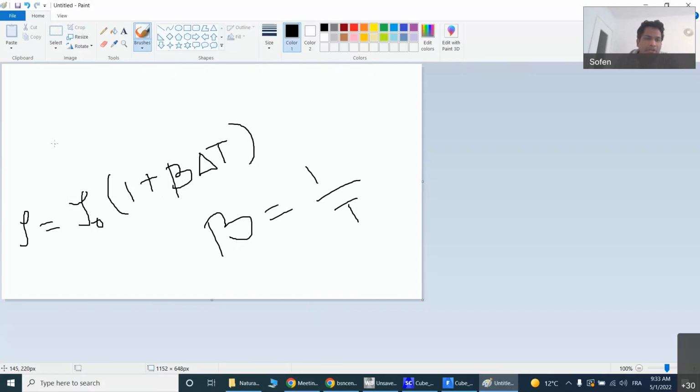Suppose you are solving a natural convection problem, you are dealing with the Rayleigh number, which is the buoyancy force to the viscous force. So g beta L cubed delta theta by nu into alpha. This is the definition of the Rayleigh number, right? And you have a Prandtl number. If you are doing natural convection, this is a fluid property.